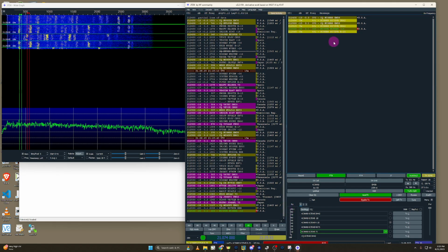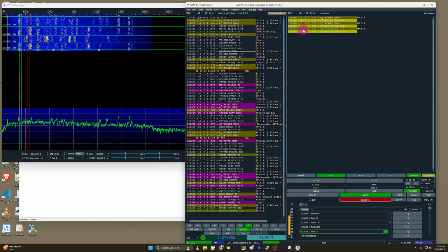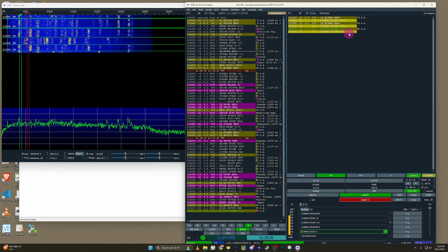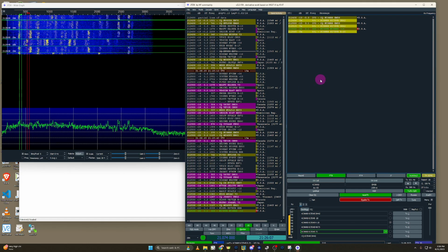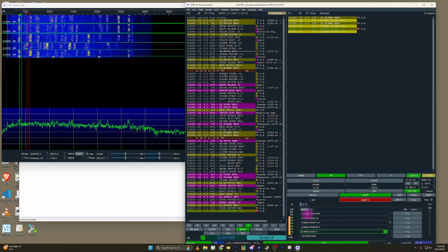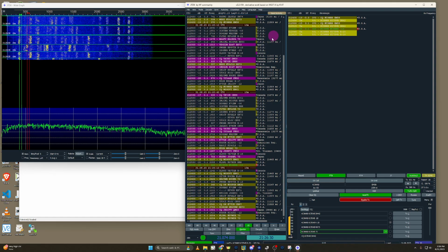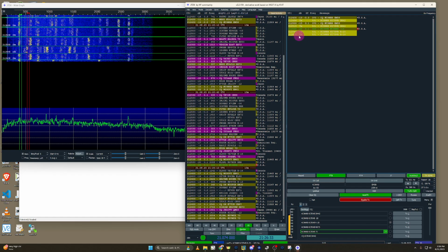Hey, it looks like our KC9NRB got back to us, and he reported that we have a negative 13 decibel signal. I'm getting a negative 20 from their side, so let's just let this QSO finish and we'll wrap up the video. I'm using the auto sequence here, which is just flowing through the QSO messages, which have been automatically generated as soon as I clicked on their CQ call over here on the left. I found that as long as the dB is better than negative 24, you'll have a reliable QSO.